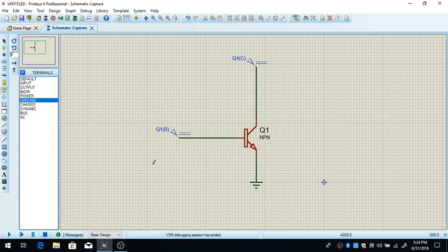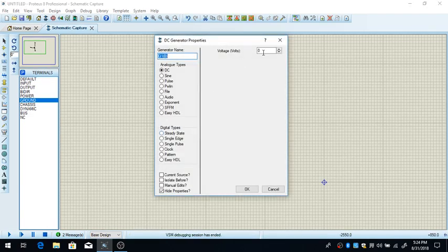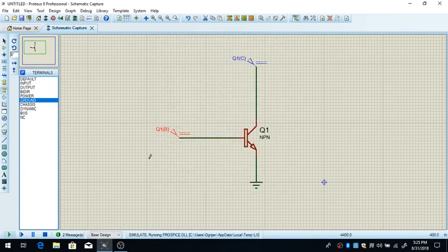So you have to bring a positive voltage to the base, like 1 volt, no matter, and then when there is a current passing through the base, the current can go through the collector and through the emitter.